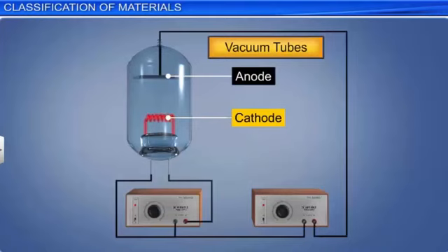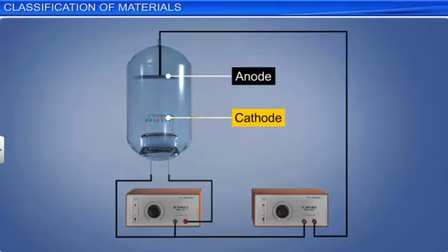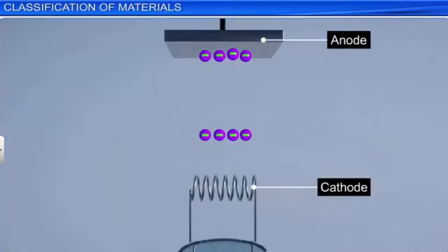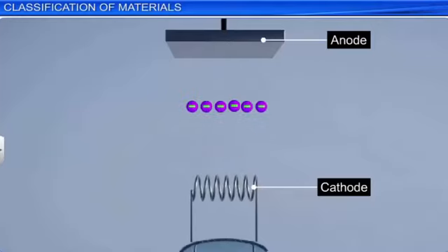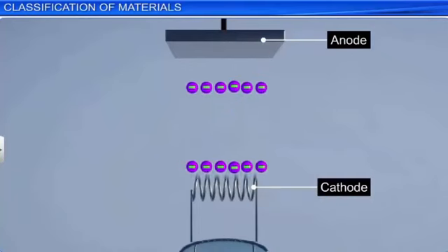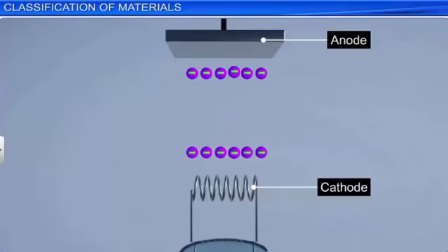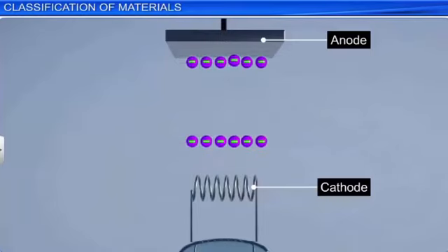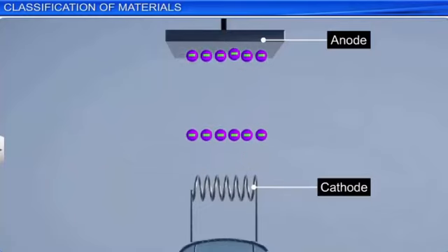When the cathode is heated, energy supplied to it helps the conduction electrons to overcome the electrostatic attractive force of the surface of the cathode, and they are set free to leave the cathode surface. The flow of the electrons is controlled by varying the voltage between the two electrodes. Vacuum is essential in the inter-electrode space of a vacuum tube, as it helps to prevent any loss of energy that would otherwise take place if the electrons were to collide with the air molecules in their path.